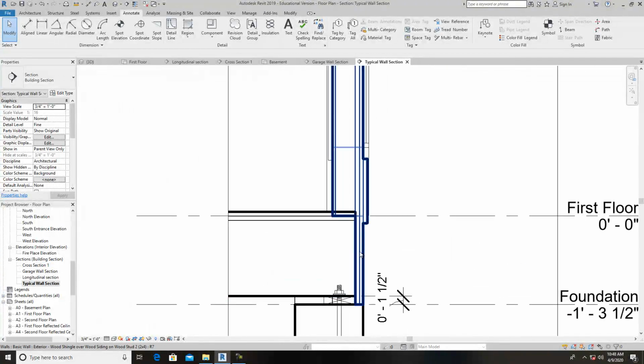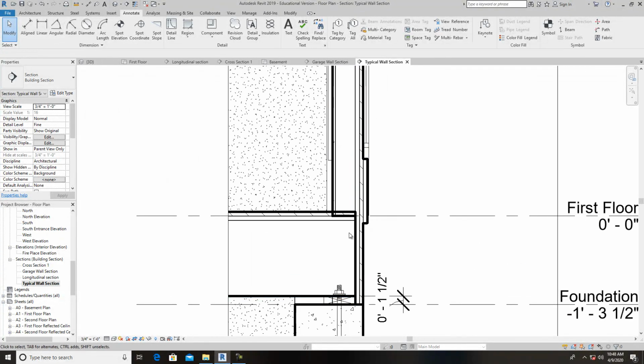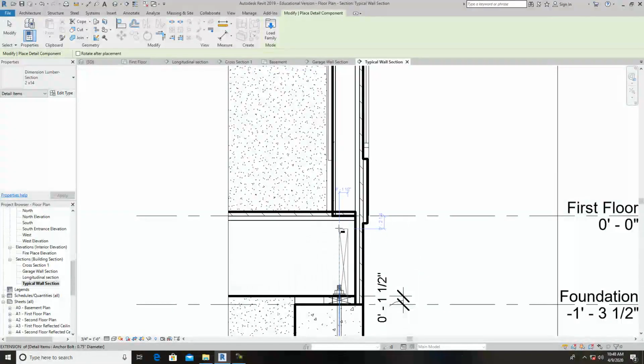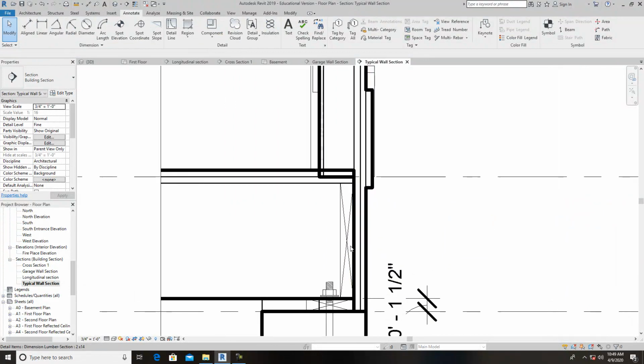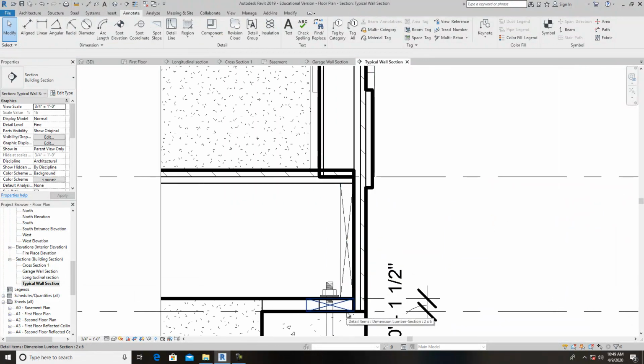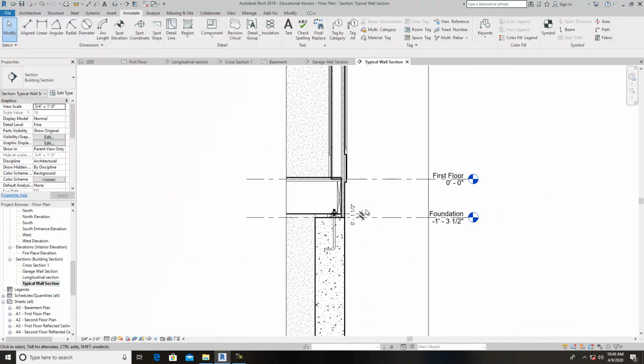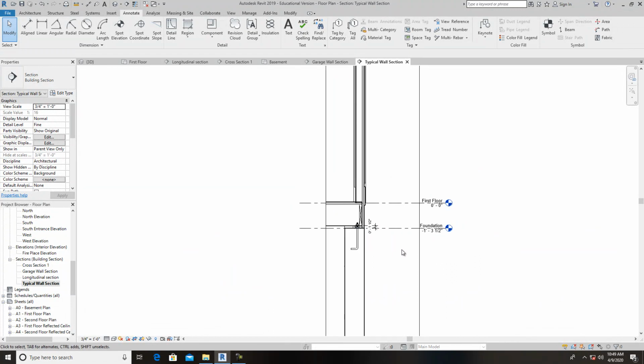Everything's looking good. Also, we'll have a header board on the back end of this, and I forgot to put that in there. So we might have to move our anchor bolt over. Now this is, that's a big, it's a 2x14. It sure is. I couldn't remember what size. This is our header board. Some people call them rim joist. Goes right there. That'd be perfect. It didn't hit. I was afraid it hit my bolt, but it's all good. Everything's looking great.